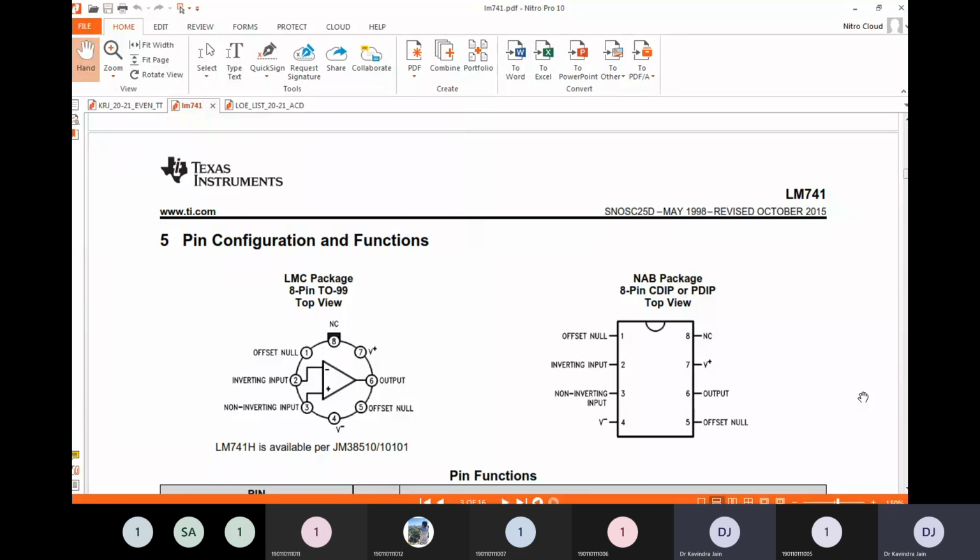So in the case of operational amplifiers, a rheostat or variable resistor is connected between pin number 1 and pin number 5 to nullify the output, and hence it is known as offset nullification, to nullify the offset voltage that is received at the output without providing the input. Is it clear? Should I repeat?